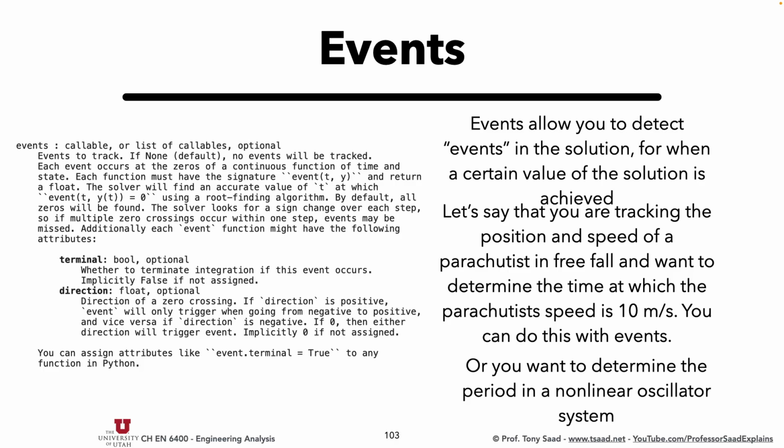So this is technically a nonlinear solver. And so the event is nothing more than the residual form of your event. Okay? So if I'm trying to find the time at which the speed of the parachutist reaches 30 meters per second, my event is v minus 30 because it's going to solve event equals 0. So v minus 30 equals 0 means v equals 30, right?